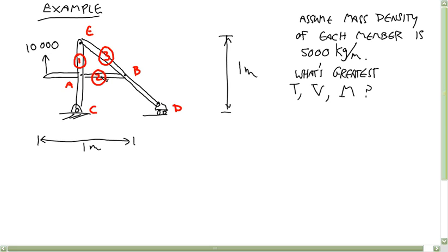I didn't take off points for doing this on the exam, but since we're going from the external loads to calculating the internal loads, when you calculate the loads of this structure, you're going to treat all those distributed loads as point forces. But when you draw out the members with their external loads at the end, draw them back as distributed loads, okay? Because that's what we're going to have to use when we go into the internal load calculation.